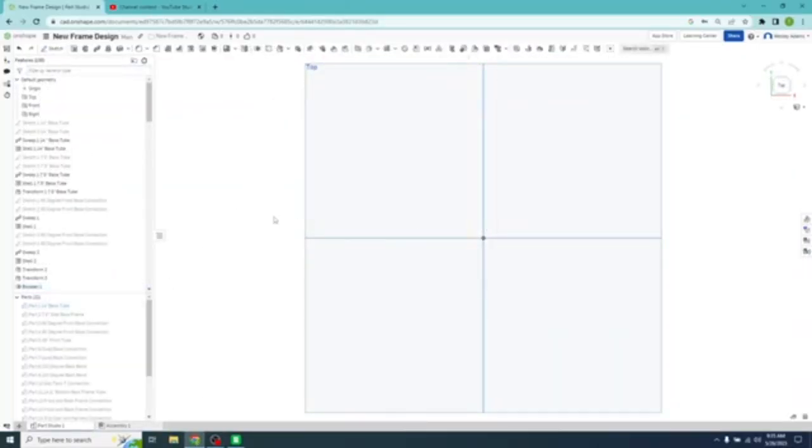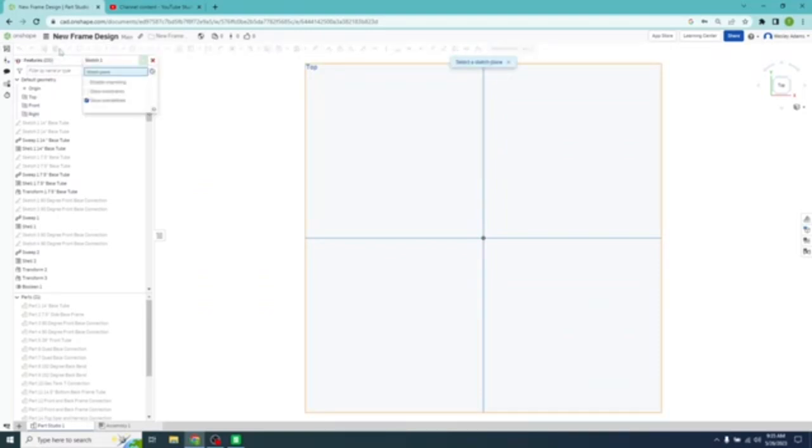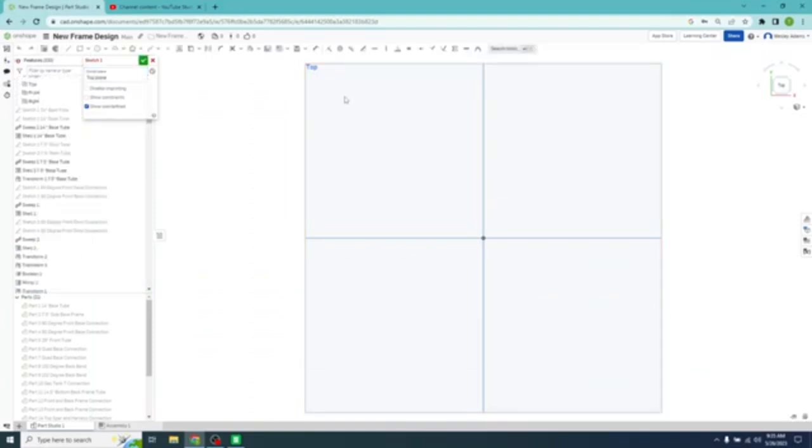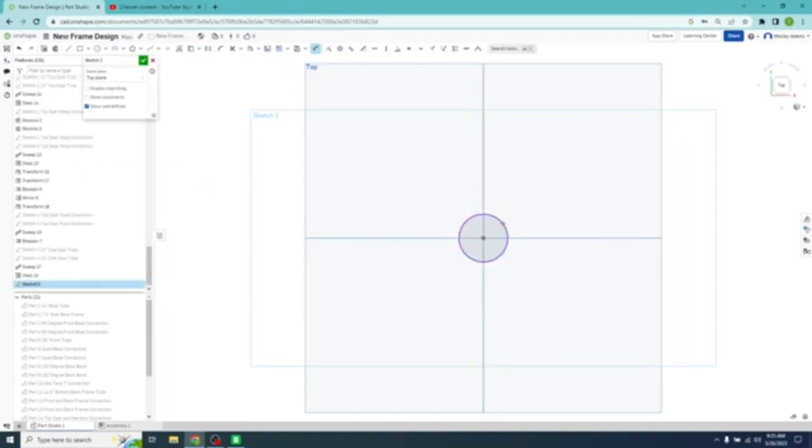Okay, let's create a new side spar fitting because we're going to have to print those off too. Let's go create new sketch. Select the plane, center point circle, hover over the center and drag. Left click on the dimension tool up here. Left click again on the outer part of that circle. Let's make this 0.5. Select another center point circle, hover over the center, left click, draw that out. And let's make that, go up to the dimension tool, make that 1 inch. The larger circle. Good.